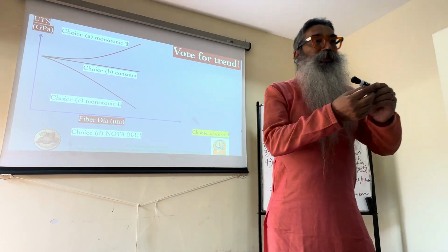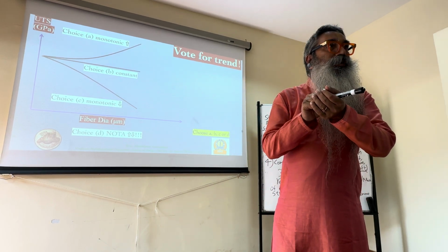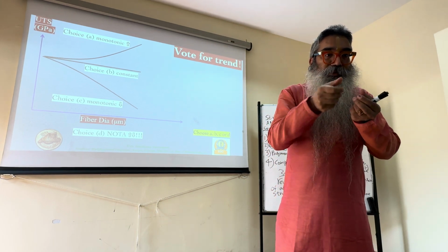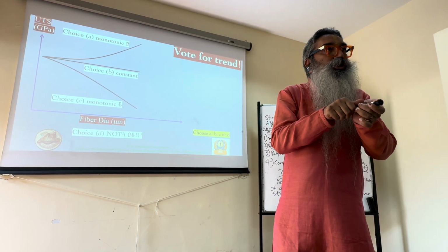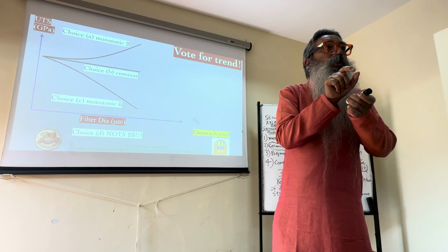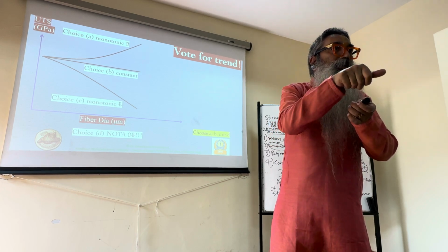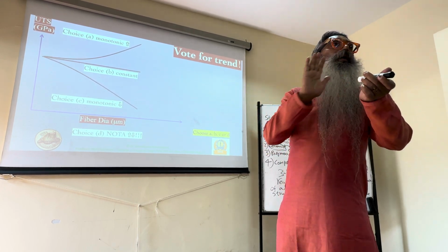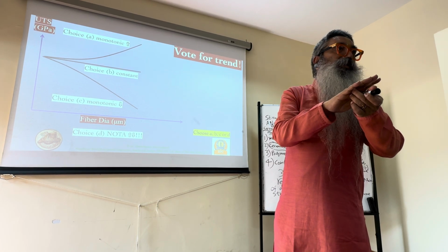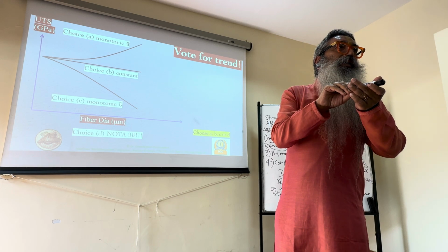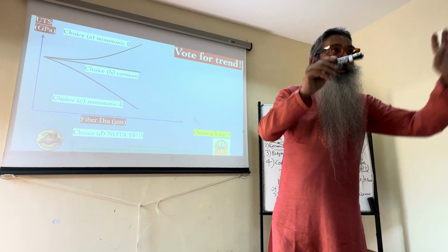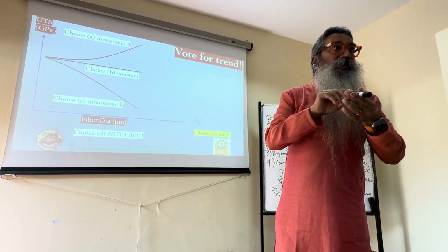The manufacturing process. For example, some fibers are made by extrusion, like your toothpaste. When you press it out, how the toothpaste comes out. So like that, if I get the fiber made through an extrusion process, I can keep the hole of that nozzle different, and for each diameter of that hole I get different diameter fibers. But the material that I'm pushing through is the same. It is the same carbon in terms of its crystalline structure, everything is the same. So I'm just trying to push it out. I'm not saying this is the way carbon fibers are made, but I'm just trying to oversimplify things for the sake of this question, right?